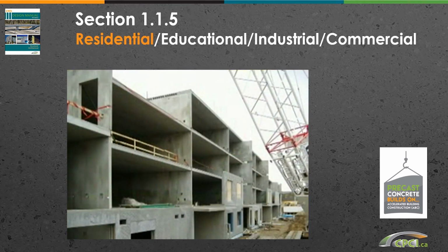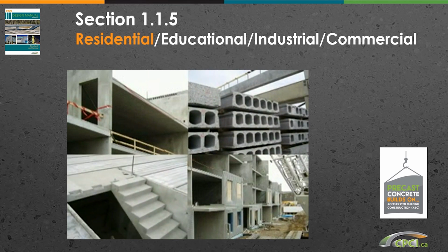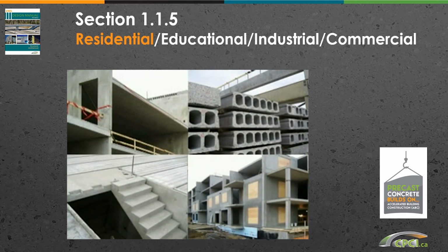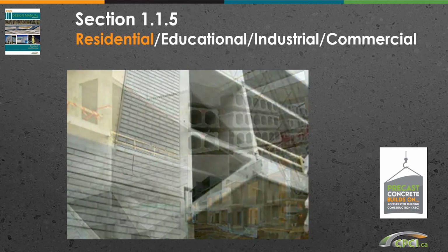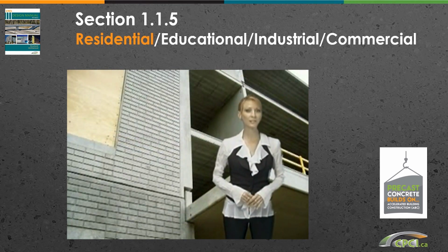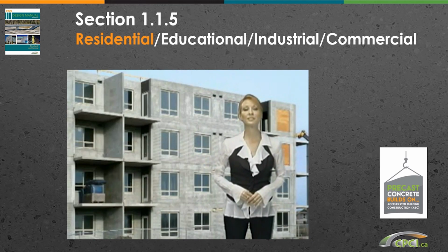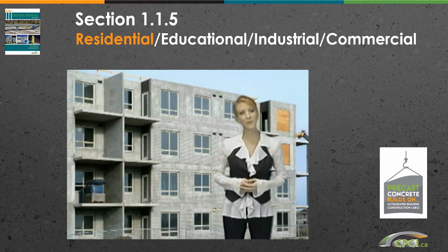These residential buildings are total precast concrete structures built using columns, shear wall panels, 10-inch hollow core floor slabs, elevator and stair cores, including stairs, exterior architectural precast insulated sandwich panels, and balcony units. The total precast structures feature an insulated wall system that serves as the building envelope. Windows are pre-installed at the plant. When the panels arrive on site and are installed, the wall system is complete. There is no need to hoard the building to create a temporary heated space.